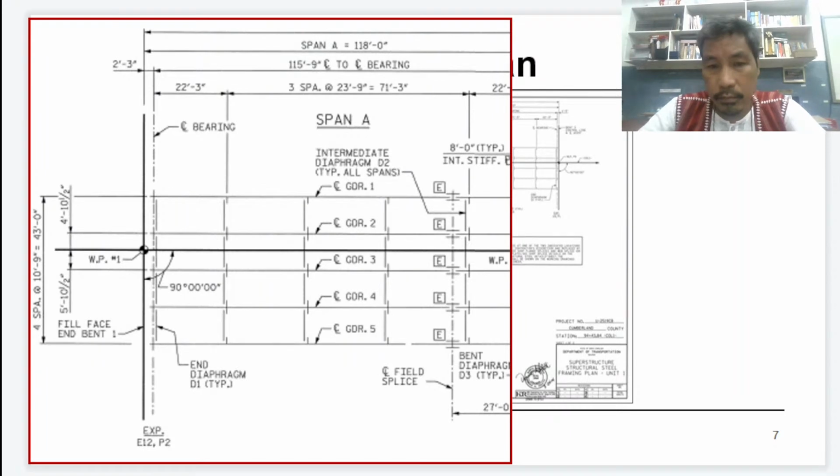Buildings and bridges are slightly different because in construction of bridge, we have the geodetic engineer responsible for giving us the reference point and reference lines. While in construction of building, because we are economizing on the cost, we don't even need to involve the geodetic engineer.